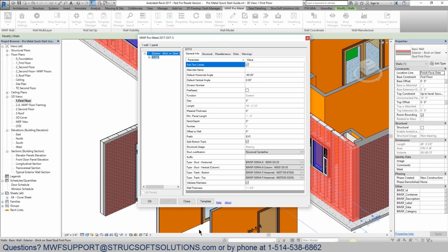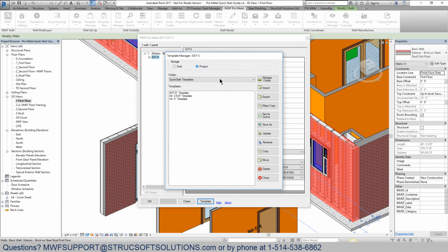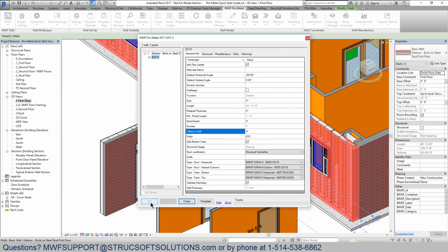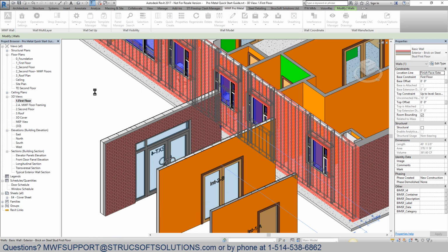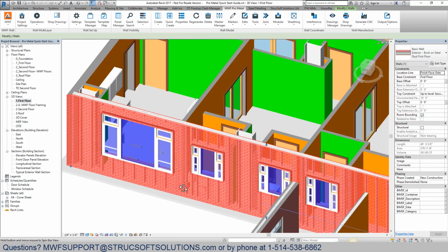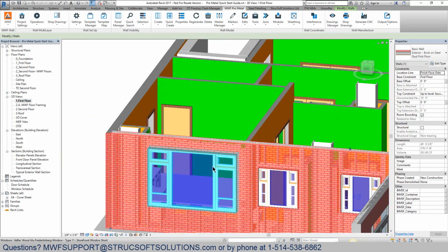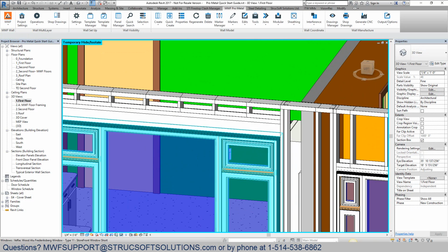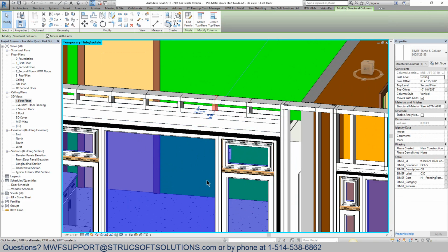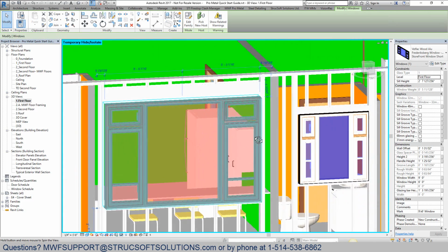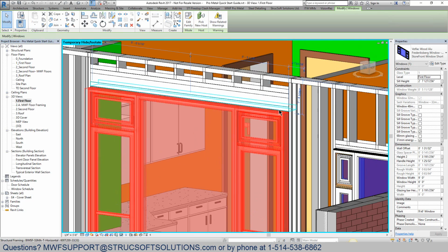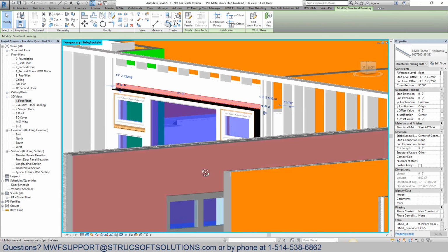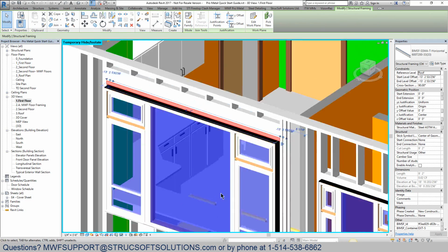And then I'm going to do it this way. Say Template from the properties of my long panel here. I set it as active. I close it down. I say OK. And with that new 1-inch minimum cripple length, those members above my window, if I take a look right here, are now being generated. There they are, little guys in there. Perfect. And I take this time to just mention too, you'll notice how my header now is sitting right on top of my window, right where it needs to be. Perfect.